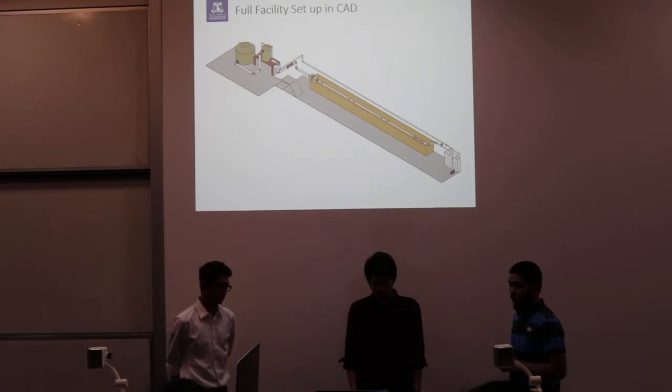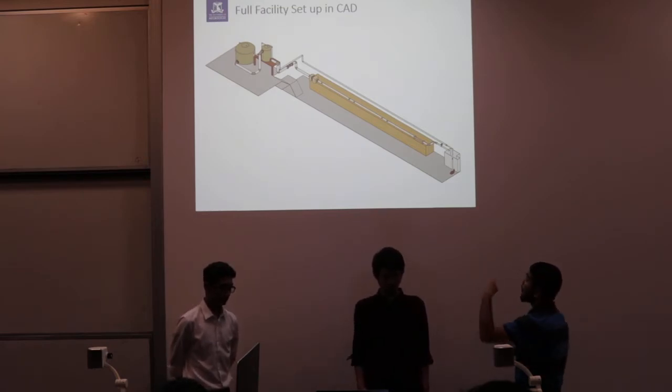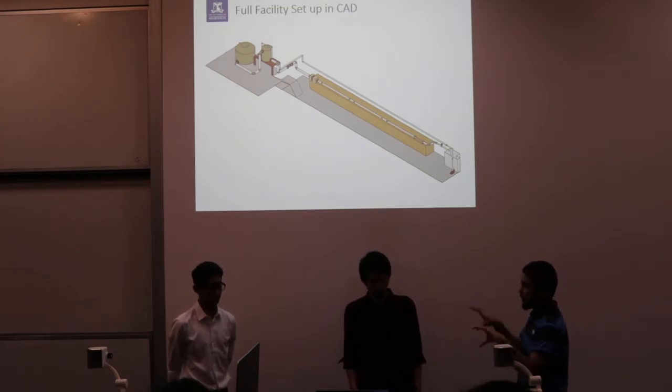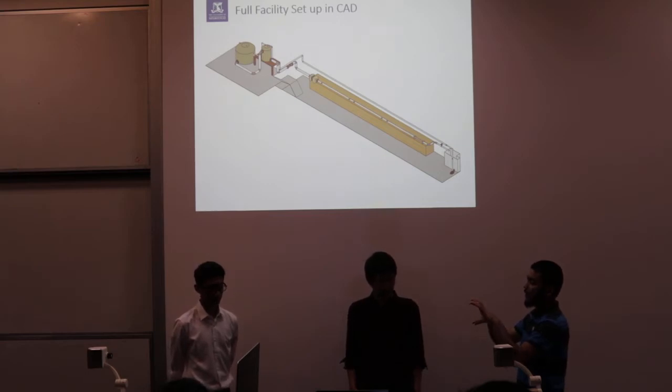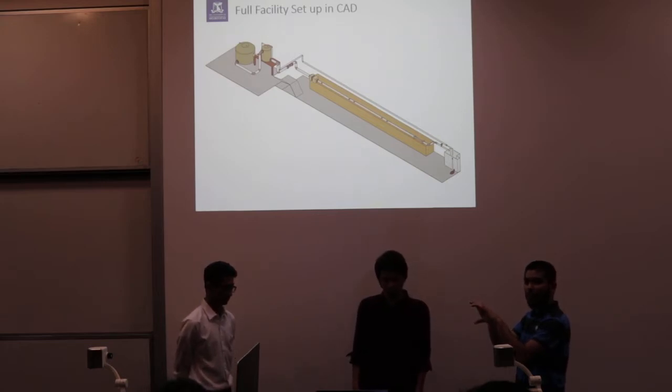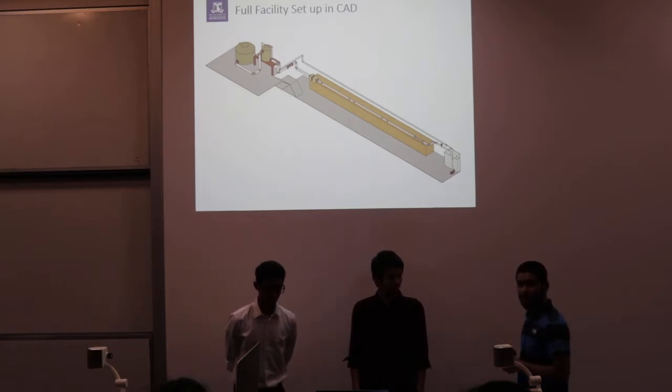When we join the pipes, they have to be squared, and when the two pipes meet, you cannot have any significant bumps. That's a key challenge when you don't have advanced machine tooling available.